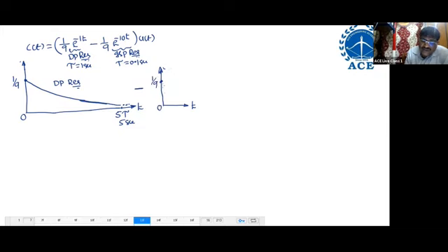That means it exponentially decays, and it decays very fast, within 5 tau. 5 tau means, with tau 0.1, within 0.5 seconds it reaches the steady state. Now you subtract the insignificant pole response from the dominant pole response, then you will get the exact response. That is called C of t.